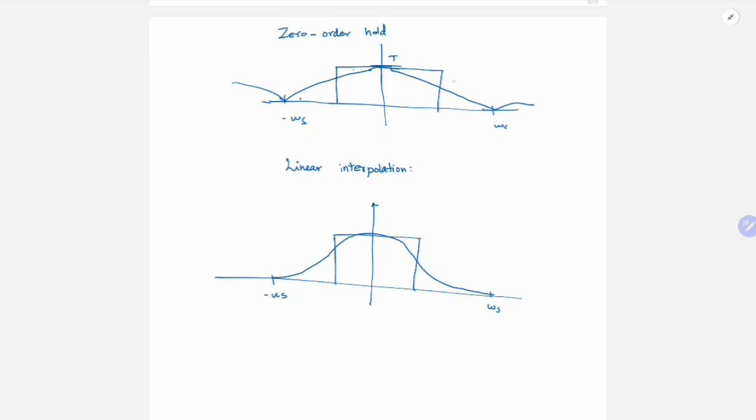So you can see this much is the error we are making if we leave the signal as it is. After you have applied the zero order hold and linear, you have to pass it through another filter such that the multiplication of this zero order hold with the new filter will give me back this ideal filter, if you have to reconstruct the signal ideally, right? Otherwise, if you only pass it through this one, you will just get these kind of signals. And in the linear case, you will get this kind of signals, right? So that is what you need to understand.